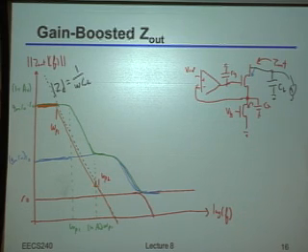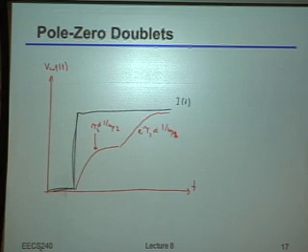Actually, even after the feedback, it would still basically be in the same point, because it turns out the pole and the zero would just meet with each other. And that pole would actually dominate your overall settling response. In other words, rather than getting something that very quickly responds to the step that you put in, there'd be this long, slow tail that may not get you to the precision that you wanted. Now, it turns out that how far apart the pole and the zero are spaced from each other also sets how big this residual settling you have to do from that long, slow pole would be. But it's fairly easy to work out exactly what that relationship is.